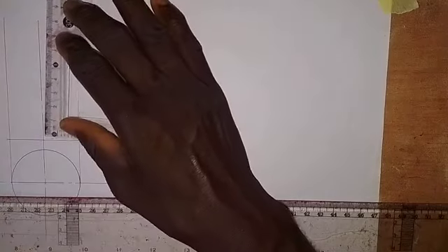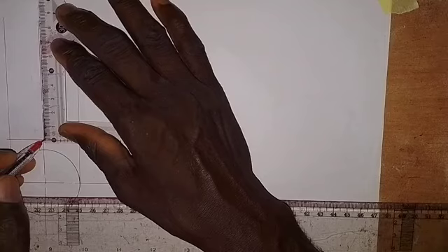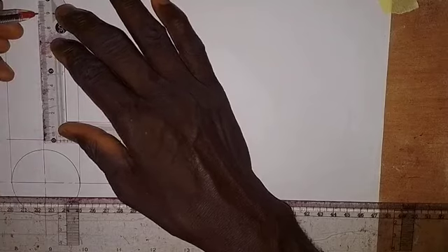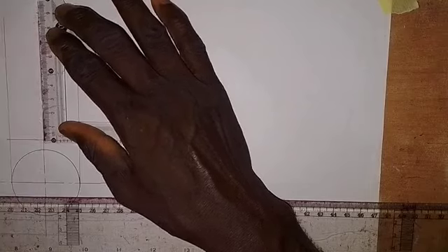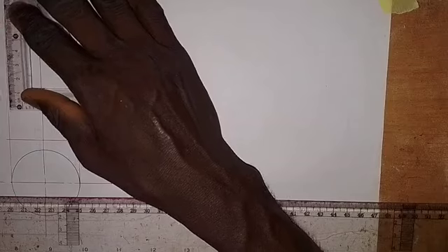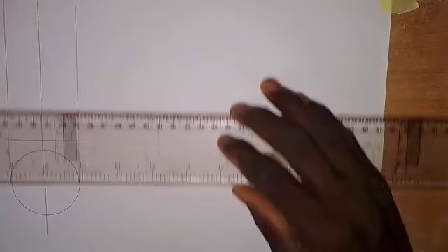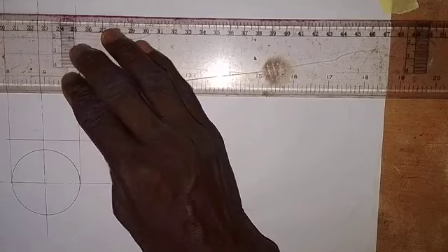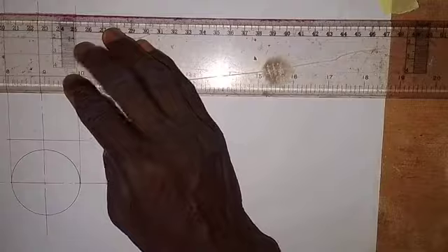Now we take a measurement of 90 millimeters from this point on the front elevation of the vertical cylinder, taken at the center here. So this is 90 millimeters. I will need to extend this center line a bit, and also extend these lines up a bit. Then I come up here and draw a horizontal line through this point. So we have this now.